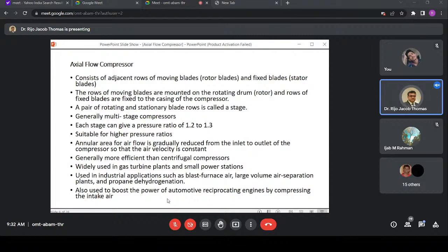So that's called a supercharger. A turbocharger is exactly when you take the exhaust gas, use its pressure to rotate a turbine, and feed its output to the engine, basically again for more power. But one is done at the suction side, one is done at the exhaust side. Okay. Supercharger is usually used in heavy vehicles, lorries, buses, big trucks, and there they use these axial flow compressors. So this is what I said. You can see that the area is reduced.